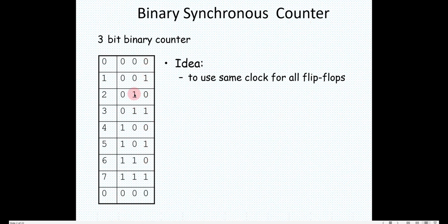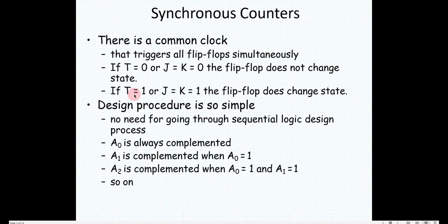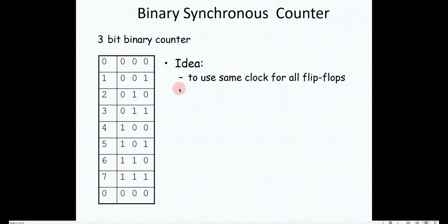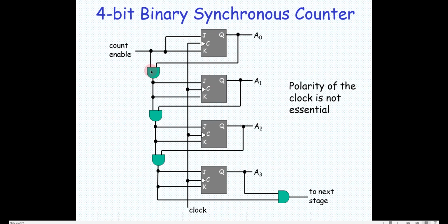Now the second one, okay, I have to give only when this is a 1 out here, right? Only then it has to make a transition, right? So I am putting this clock enable signal also here. Okay, if this is 0, nothing would move. So this is just to enable all the circuits. So I am taking this Q and giving it here, right?